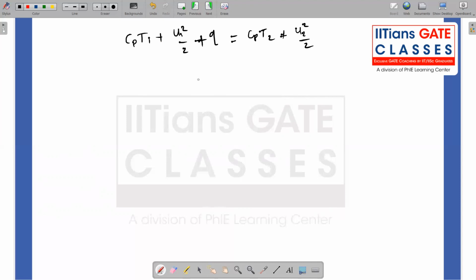So I can write for the heat alone, Q is equal to Cp times T2 minus T1 plus 1 by 2 times U2 square minus U1 square. Or I can write in another form, what is this, Cp T plus U1 square by 2? Locally, this is nothing but a stagnation condition, right? With the assumptions, whatever we consider for the definition of stagnation temperature. So for a calorically perfect gas, this is nothing but a stagnation temperature.